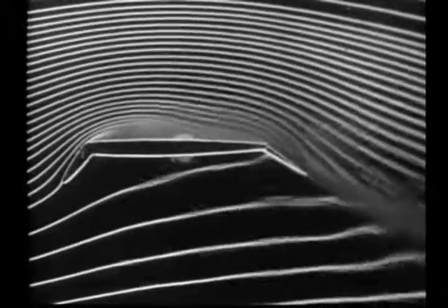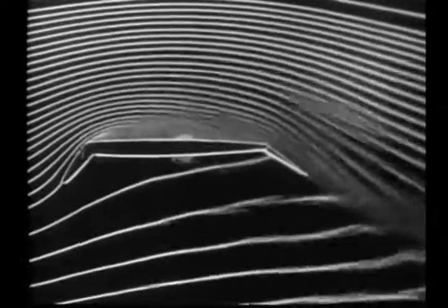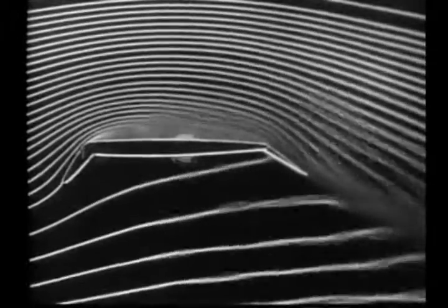Separation at the leading edge flap break still exists because of the small radius of curvature at this point. To approach the potential flow pattern, it is necessary to overcome this separation by diverting some of the air now being blown over the trailing edge and to blow it over the leading edge flap break.